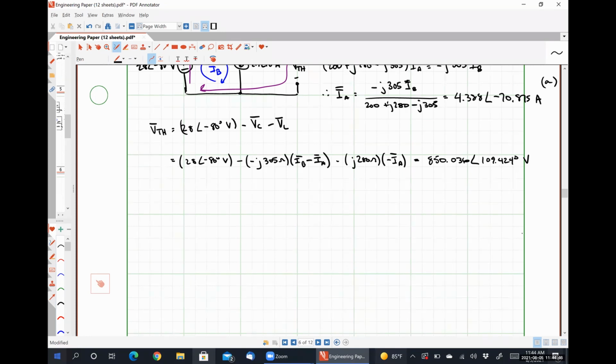So if we were to try to find the Norton current, what we would do is we would short out that impedance ZL and find the current flowing through that impedance ZL. That would require us to set up a nodal analysis system where the only unknown voltage would be the voltage drop across the current source.